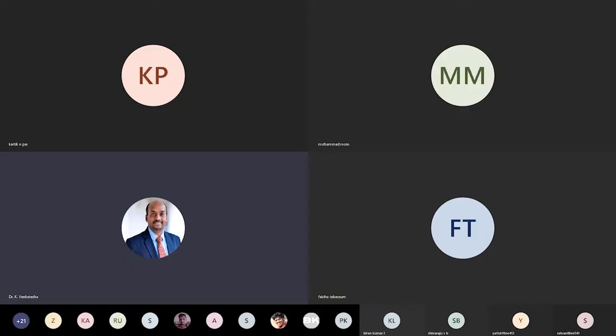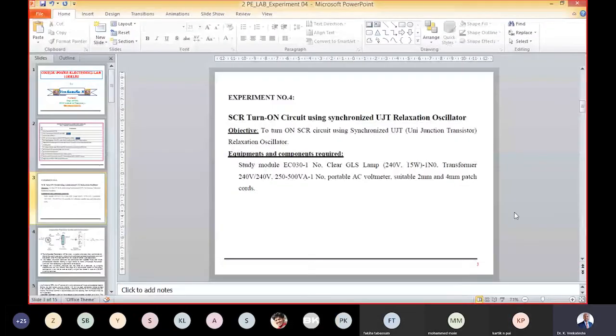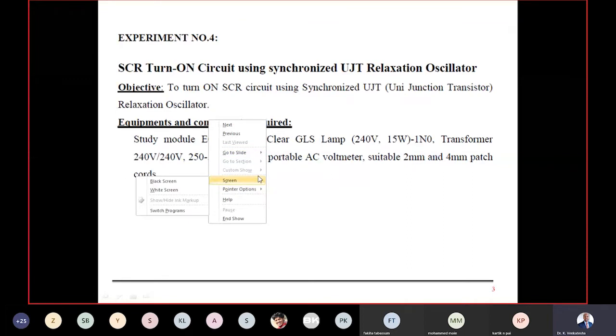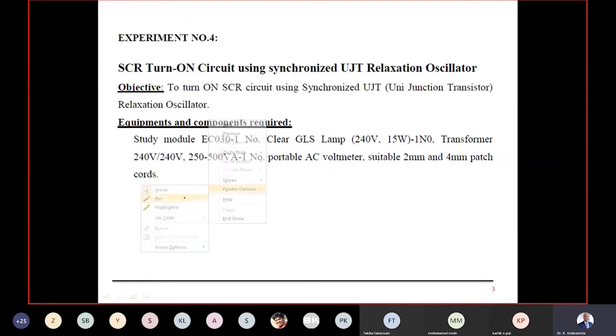So the main important key roles I told here is that one is my turn on circuit, which means that my circuit is capable of turning on SCR. I don't have control to turn it off. It has to turn off automatically. Okay, that's with the line commutation.